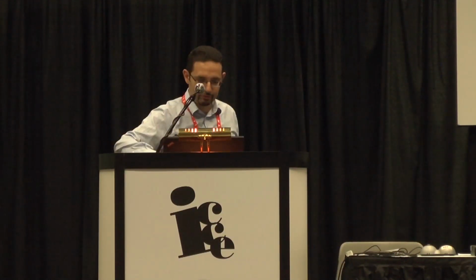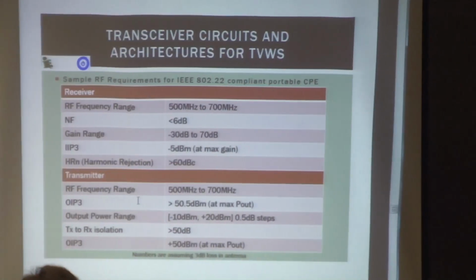They've defined how to detect an analog TV signal or digital TV signal to be able to not interfere with those. But then you can have other unlicensed equipment out there, like Wi-Fi, for example, that can transmit at their data rate, at their frequencies and everything. But as I showed earlier, if you go back in these slides, for example, there's a harmonic rejection requirement. So you have Wi-Fi being transmitted at 2.4 gigahertz, for example. If there's any transmission there and you're trying to receive a signal that's a third of that, that's a problem for the TVWS.